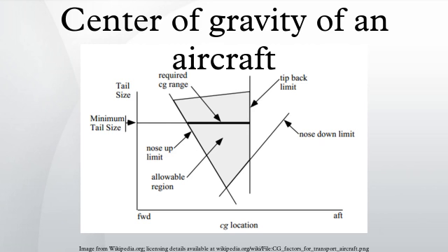In order to make such a calculation, the position of the leading edge of the MAC must be known ahead of time. This position is defined as a distance from the reference datum and is found in the aircraft's flight manual and also on the aircraft's type certificate data sheet. If a general MAC is not given but an LE MAC and a TE MAC are given, then your MAC can be found by finding the difference between your LE MAC and your TE MAC.